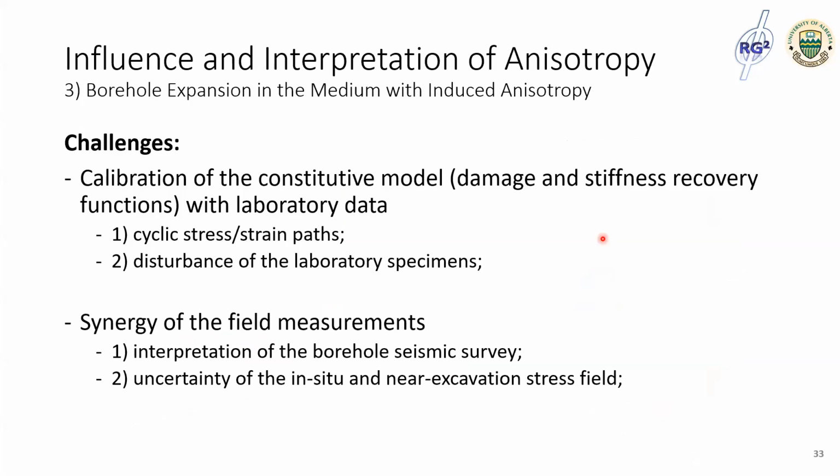And of course, this is not complete and needs more research work, particularly for the calibration of the constitutive model. We need to conduct laboratory tests that can represent the stress-strain path at the borehole during unloading and the pressure reloading. However, the disturbance of the laboratory specimen is always a concern, and this needs to be taken into account in the steps of the constitutive model verification.